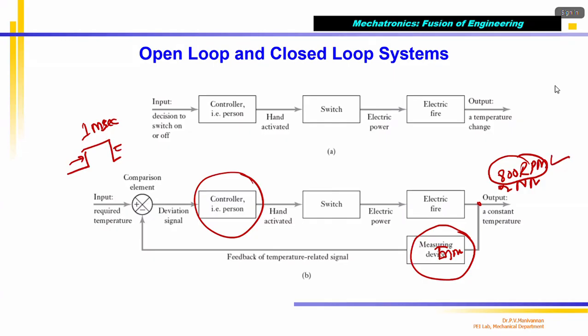But now it is not running because the amount of air sucked is the same, but the temperature is different, so the air mass is different, because the atmospheric temperature increased. Our vehicle is at a higher altitude. So the speed may be 700 or 750 RPM instead of 800 RPM, as the amount of air is less. So when you inject fuel, the combustion pressure and temperature are less, so the torque produced will be less, and the engine RPM reduces.